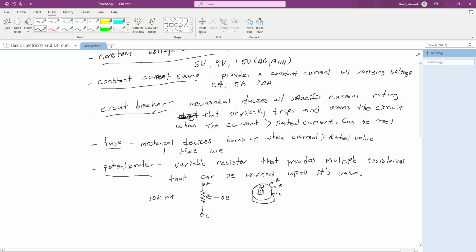So this knob is going to rotate back and forth until it gets to a hard stop, and what that does is going to shift this point either up or down, and it changes the ratio of the resistance between point A and B and between point B and C. A to C stays the same regardless of where this potentiometer arm is at. All it is doing is changing what A and B is compared to B and C. A and C will stay the same. So this is going to be the ratio of resistance.